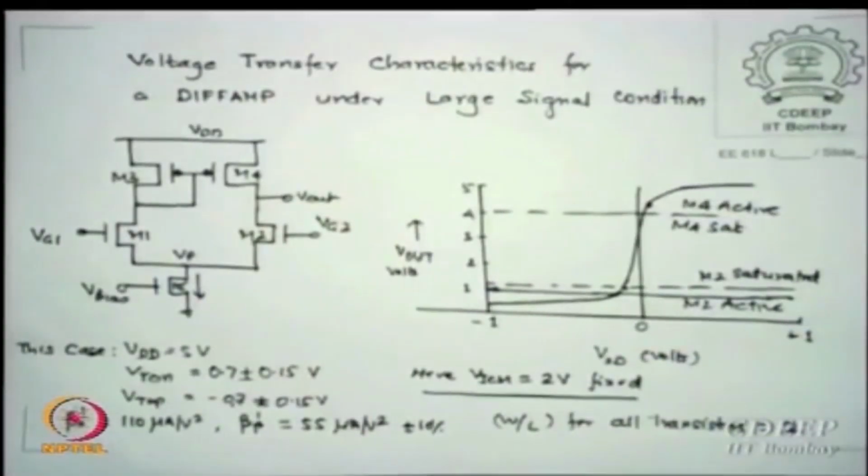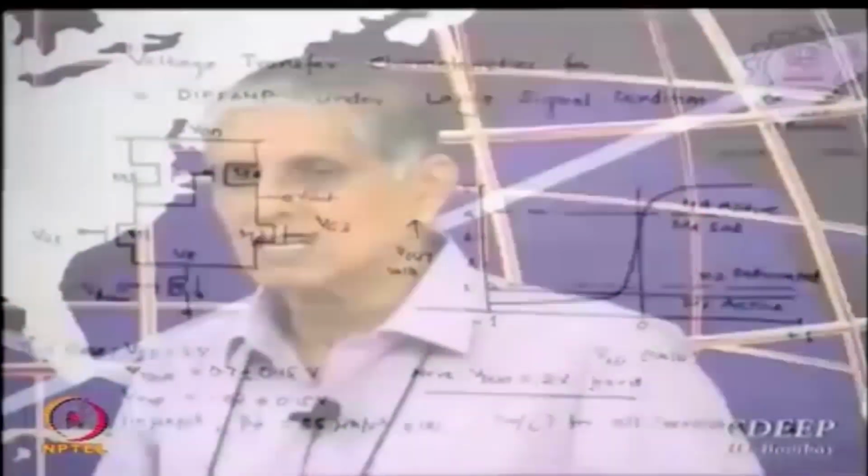Of course Spectre or SPICE does not allow so much easily, but there is a model card in SPICE which you can write yourself. So it is not that you have to only work with their default values, you can change your model parameters and still work on it if you have used a model card of your own. So do not come and say sir, that is fixed, you can always change the spec of your choice by putting another model card there. I am not sure whether NG SPICE or SPICE 2G 3.3 has that, but just figure it out. The model card allows you to specify all mu's, TOX, everything of your choice. Please take it, these are some issues of interest.